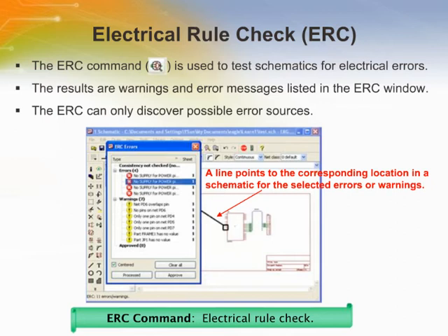This will only help in pinpointing some of the more obvious problems. If the ERC comes up with any warnings, you should try to pinpoint and solve the problem before moving on. Sometimes an error message or warning can be tolerated. In this case, you can approve to ignore them. Once all ERC errors and warnings have been eliminated, you can go on to routing the circuit board.